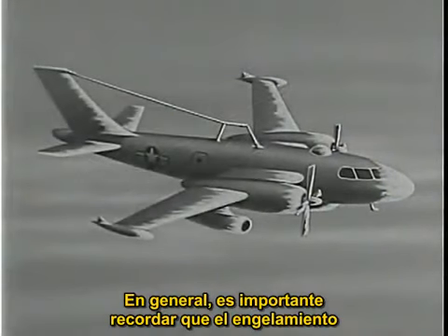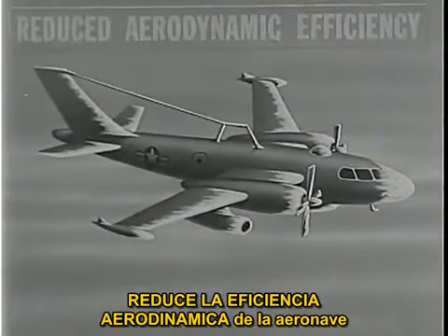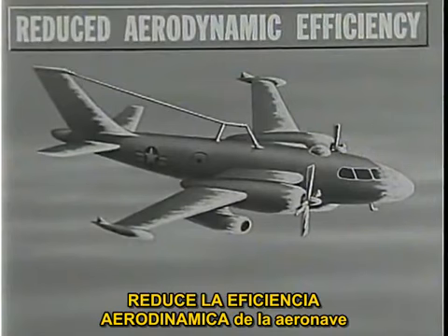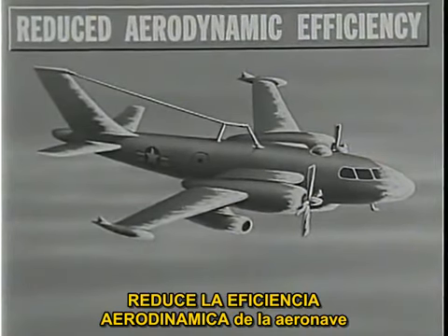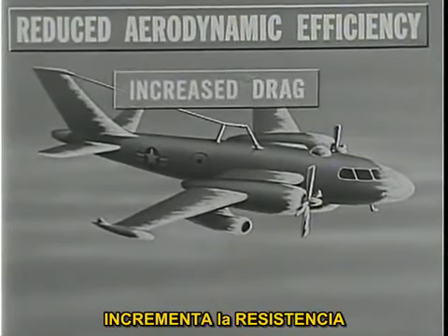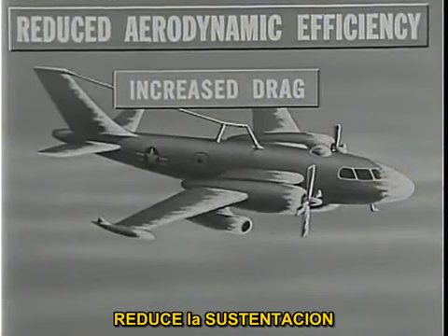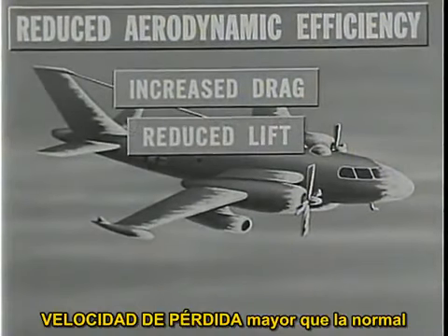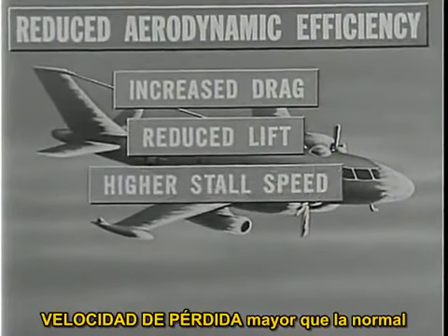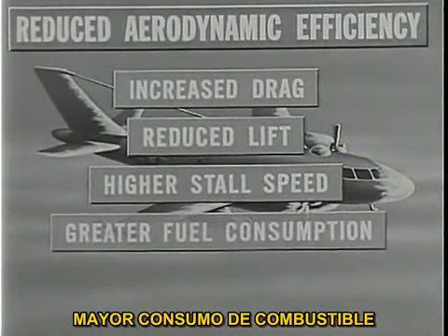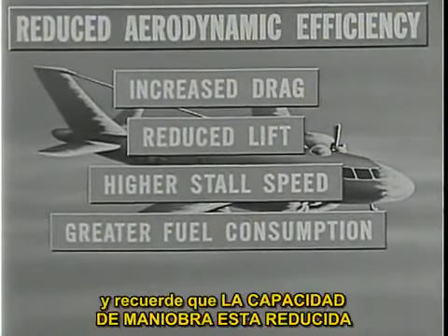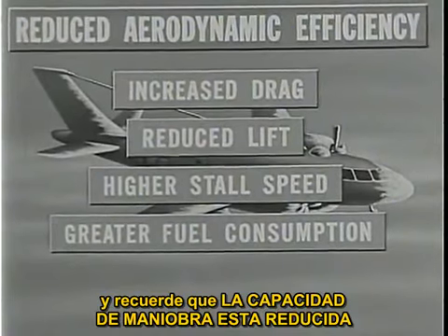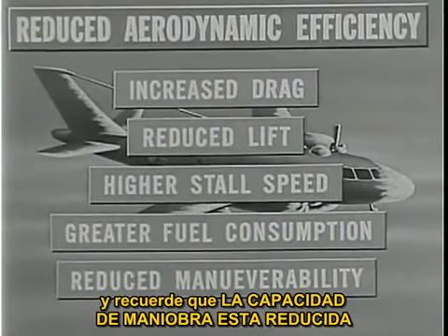In general, it is important to remember that ice reduces the overall aerodynamic efficiency of the aircraft. It increases drag, reduces lift. Stall speed is higher than normal. Fuel consumption is greater. And above all, remember that maneuverability is greatly reduced.